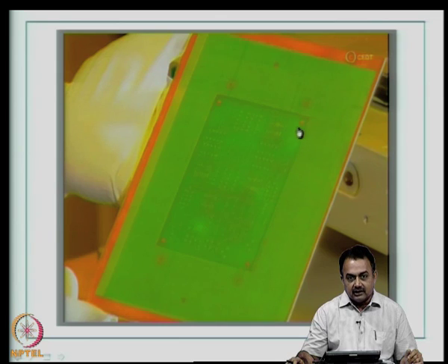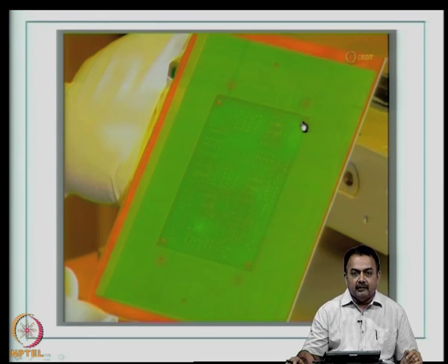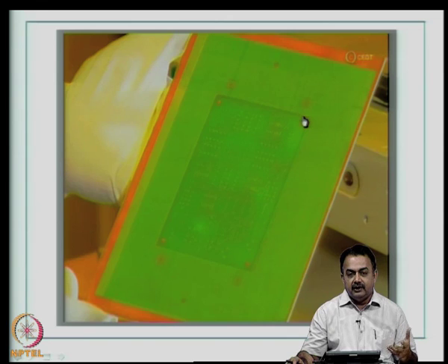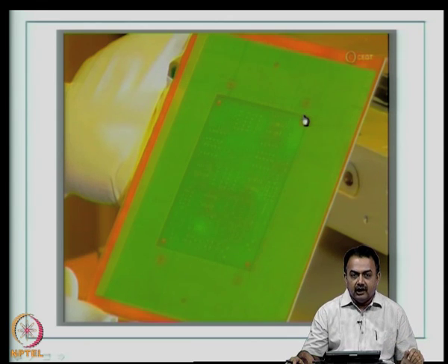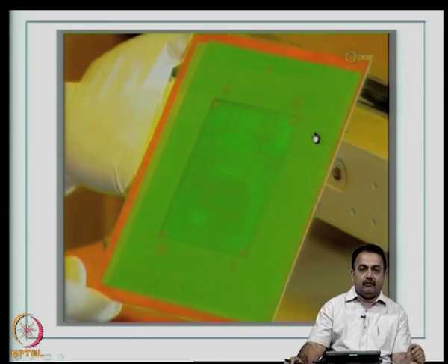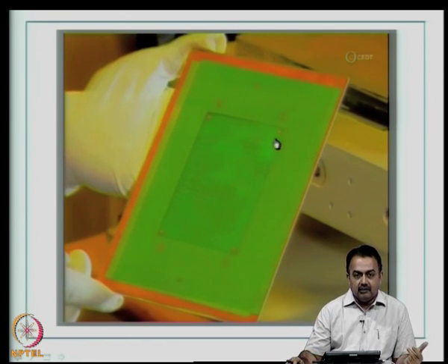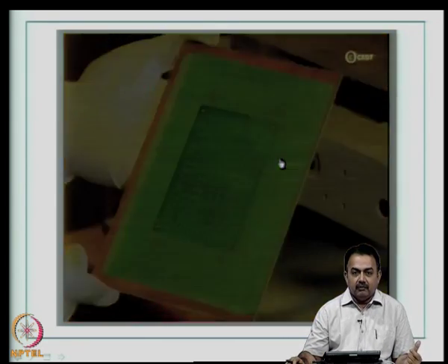Now, you are going to use a mask for the solder mask after this material has been cured in the oven at, let us say, 100 degrees centigrade for about 10 to 15 minutes. Now, you can place a solder mask photo tool and then open up the unwanted areas and remove it by developing. So, the areas, that is the pads and the tracks, or the pads will be open, other than the pads all other areas will be covered with the solder mask material. So, this screen printing is very useful for print and etch process, a solder mask process, or legend printing for printed wiring boards.